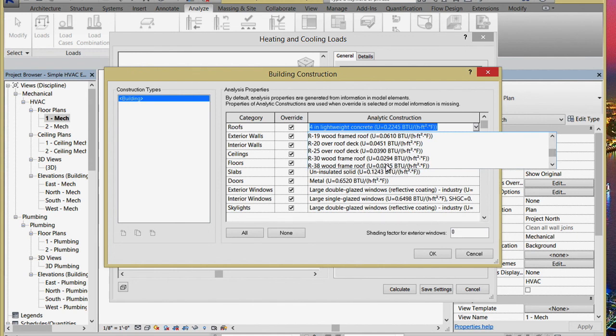You can see that the current default U value is 0.22. If we put like an R30 roof, it would be 0.02. That's going to have a huge impact in terms of the amount of heat that's going to be flowing out there. Okay, actually, let me do this. I'm going to leave the default assumptions first, and we'll see how bad the system would be sized, or how massive the system would have to be with those default assumptions.